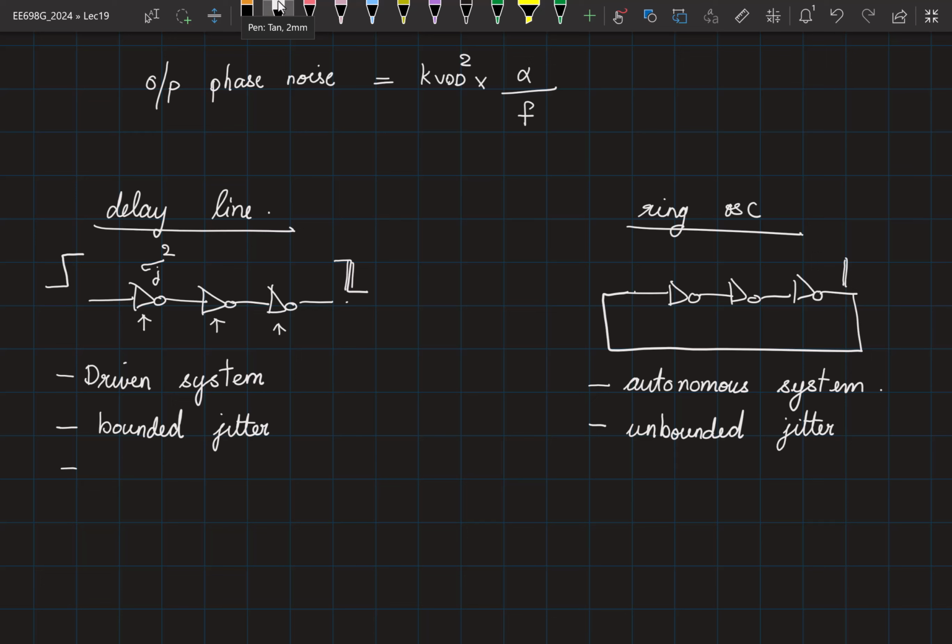Now the nominal frequency you will observe at the output here is not going to vary a lot, because the input has the same frequency. Because of the jitter, from one cycle to the next, you can talk about an instantaneous frequency. But if I were to observe it for a very long time, and if the jitter being added is zero mean, then the frequency of the output shouldn't change. Like average frequency has to remain the same.